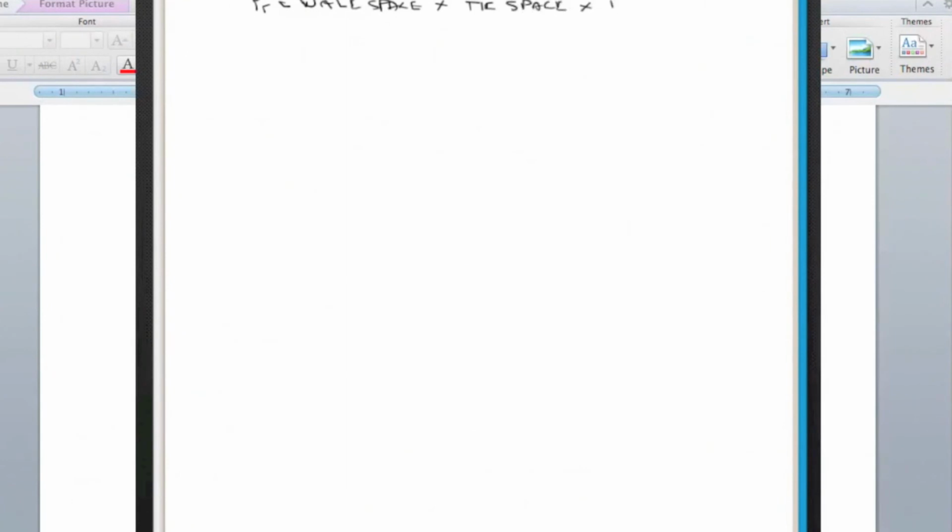times your pressure, P. So the wale spacing was 18 inches. The tie spacing we just found to be 24 inches. So let's put that in. So 12 inches, I'm sorry, 18. We used 18. And we'll just put that over 12 times 24. That's what we just designed, times our pressure of 912.5. And this is the actual force that's on this.